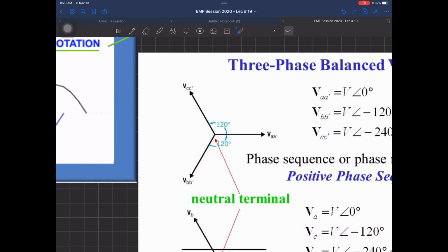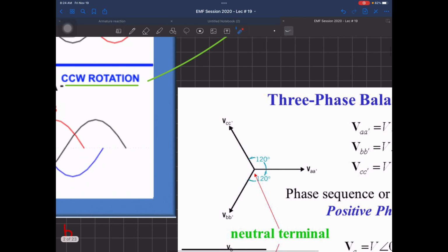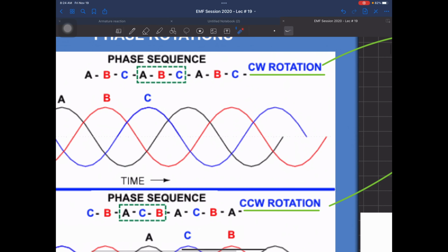Now, whenever you want to write down the phase sequence, as the word suggests, what is the direction or the ascending or descending order. So you are always going to start in clockwise direction. What I mean by this, here this will be VA, then the next one is VB, and then I continue my clockwise rotation, this will be VC. So my phase sequence, as shown on this diagram, is A, B, C. You always have to go in clockwise direction, and this is A, B, C.